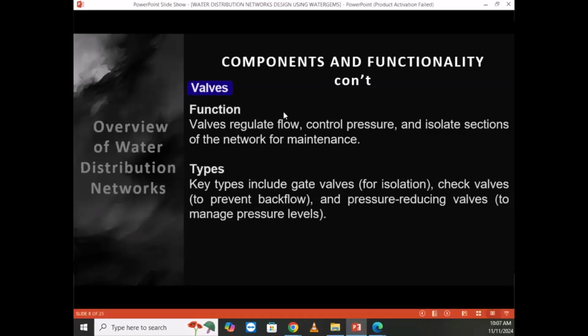So you will control that flow just at this inlet, so that the velocity and the flow will be adequate for this pipe. For us, most of the time the velocity has to go between 0.5 and 1.5. I don't know for you. It's the same?